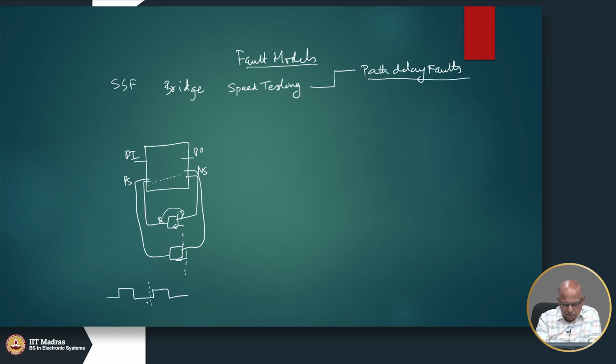So, this is a clock to Q delay, and this is a setup delay. All paths must settle down in this much time.